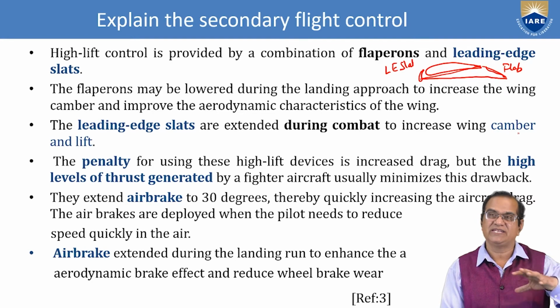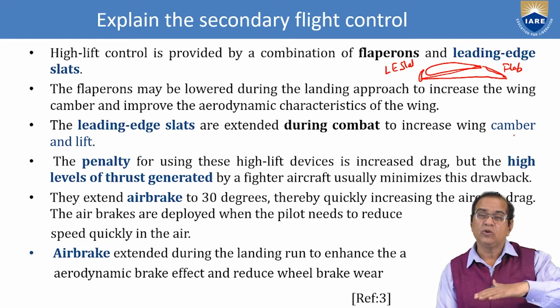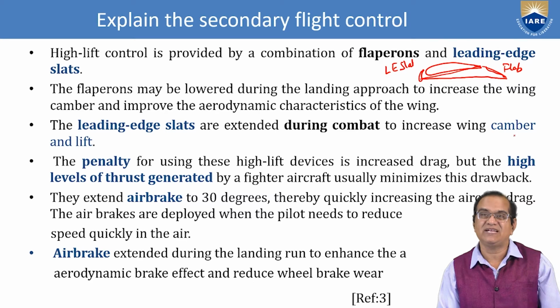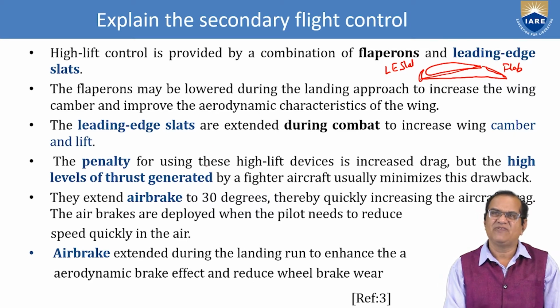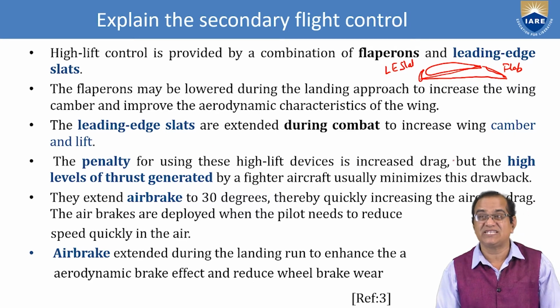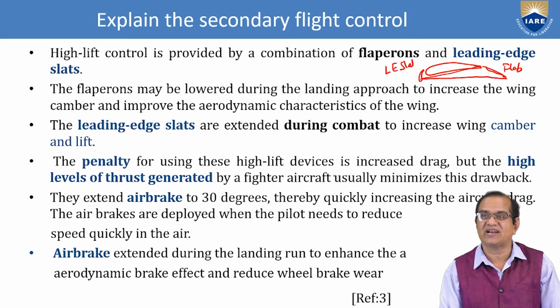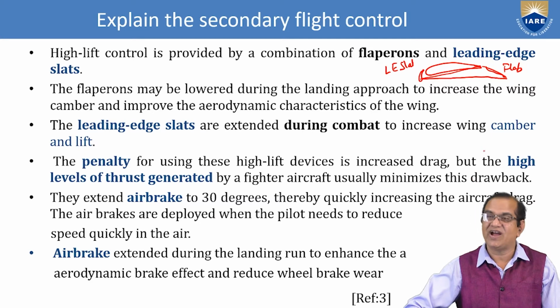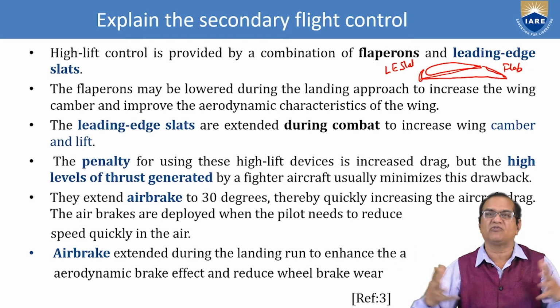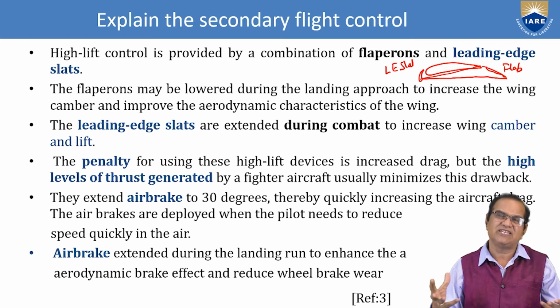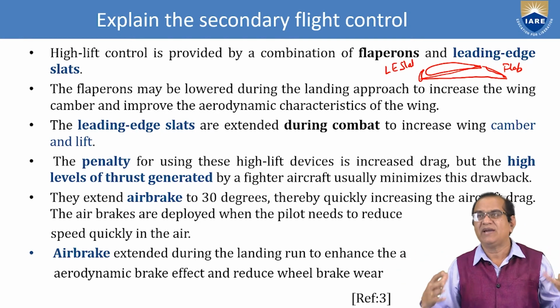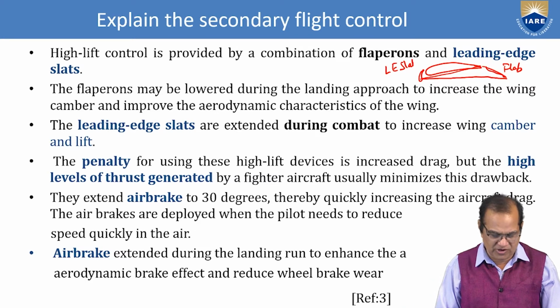So during the flight, if all of a sudden you want to climb, you have to increase the slat. The penalty for using high lift devices is increased drag, but the high level of thrust generated by a fighter aircraft usually minimizes this drawback. So there is a drawback because drag will be increased, but in a fighter aircraft, they have a sufficient amount of engine power. That engine power is able to handle the high amount of drag.